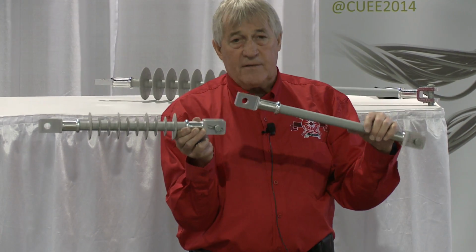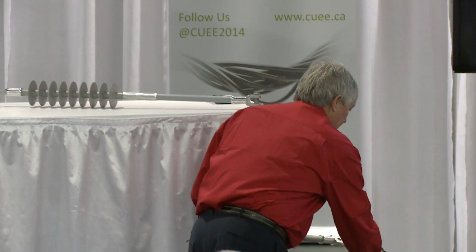That's basically the same test that a line post insulator or a dead end suspension insulator has to meet in the CSA standards. So what they're saying is, when it says shall, as you know in the standards language, shall means must. So it's compulsory, if you're going to meet the CSA standard, that you use a guy strain insulator or a specialty device that will meet that 1,000 hours on the tracking wheel.